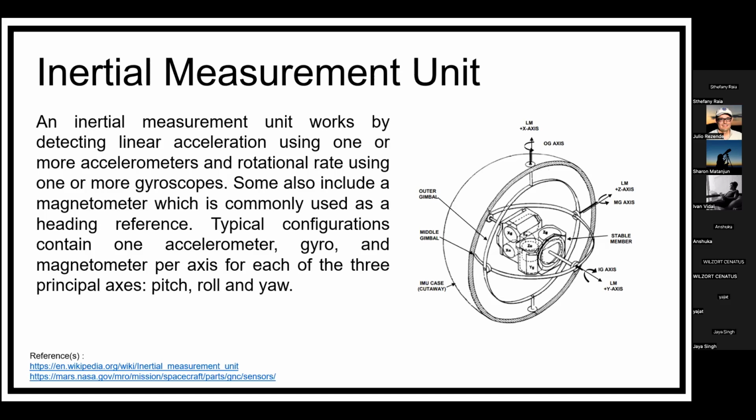These units provide inertial attitude and velocity data to a spacecraft's guidance, navigation, and control system. The IMUs are very useful in providing the velocity data of the spacecraft. On a space shuttle, IMU data are used for converting the steering commands into control surfaces, engine gimbal, or the reaction control system thruster fire commands.